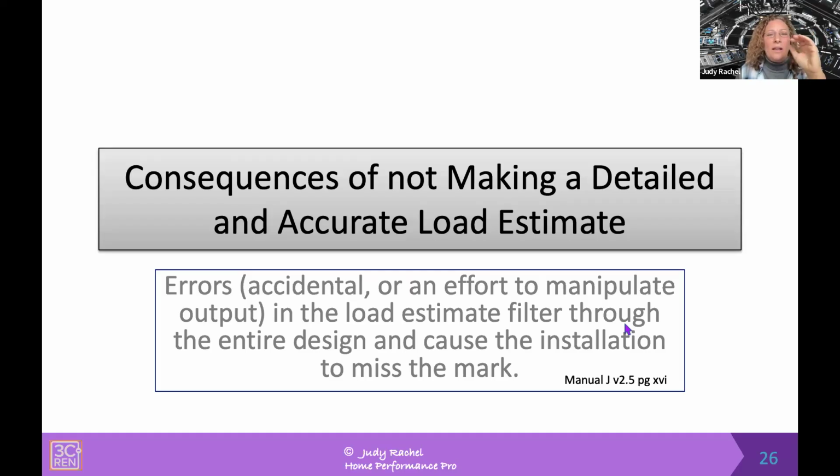So it's in that way that you're never ever going to come up with an undersized load when you do the procedures properly and you're honest and aggressive about your inputs, because all of those formulas are always rounding a bit. And even in the way that we're allowed to measure our buildings, there's a little bit of rounding up, because we're allowed to round the measurements of, say, a wall to the nearest foot. Those are the types of things that end up giving the load calculation this inherent and appropriate safety factor.